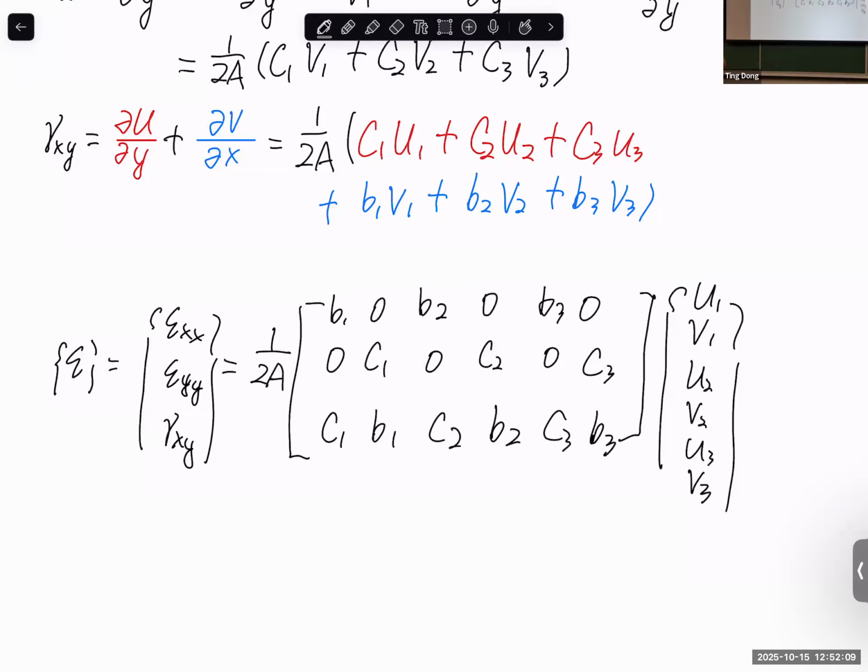So in Abaqus, you submit a job and it runs successfully, and then you check the results. In the results, it will show, let's say, displacement. It has a picture. Yeah, deformed, undeformed, stress, deformed, undeformed. And you can also plot it as overlap, like deformed and undeformed, and screenshot that one. And yeah, screenshot, yes. You don't draw it by yourself. Yeah. Any other question?